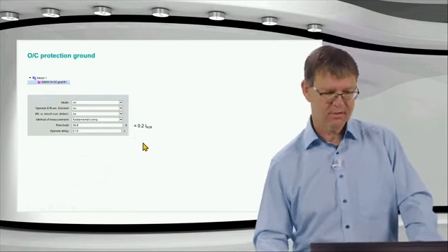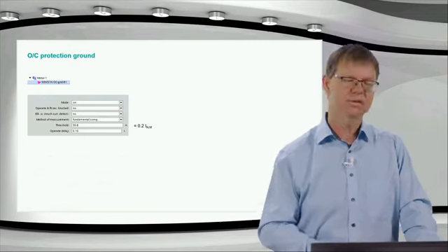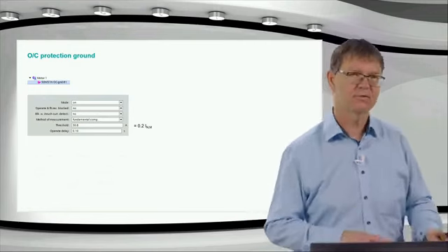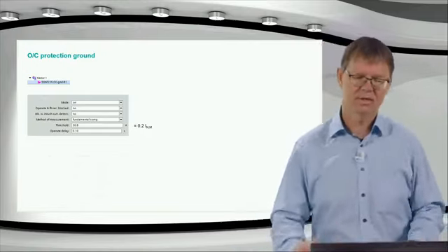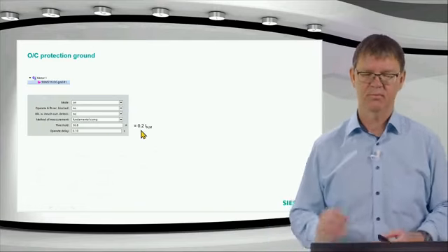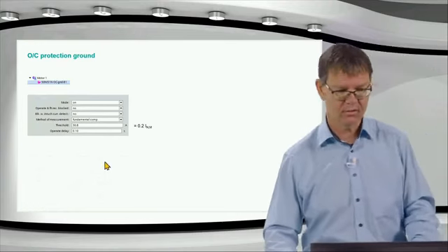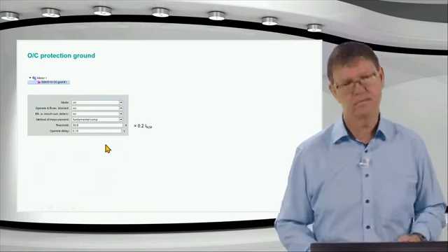During commissioning, you can check, maybe make a fault record and see what ground current comes out due to the unbalance and errors of the current transformers. When you start up the motor, maybe you can set this more sensitive, maybe to 10% of the nominal current, depending on how you measure the current, and then also a certain operator delay, a little bit longer, to stabilize this.